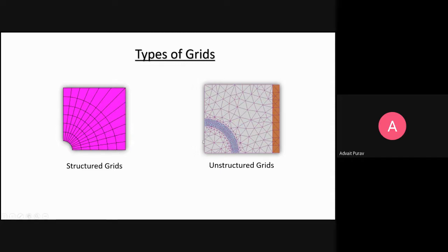But this is the particular reason for it: if a particular part's wall thickness is different, or the shape is different, or the intricacies are different, then you'll have to assign it a different size. Also, one student gave me an answer that if this is particularly my area of interest, where I want to calculate more stress, I'm interested in calculating stress of this particular area. Definitely you need to assign a finer mesh for that particular domain or part, so that you can get a more accurate result on that particular thing, and you can simulate it quite easily. Absolutely.